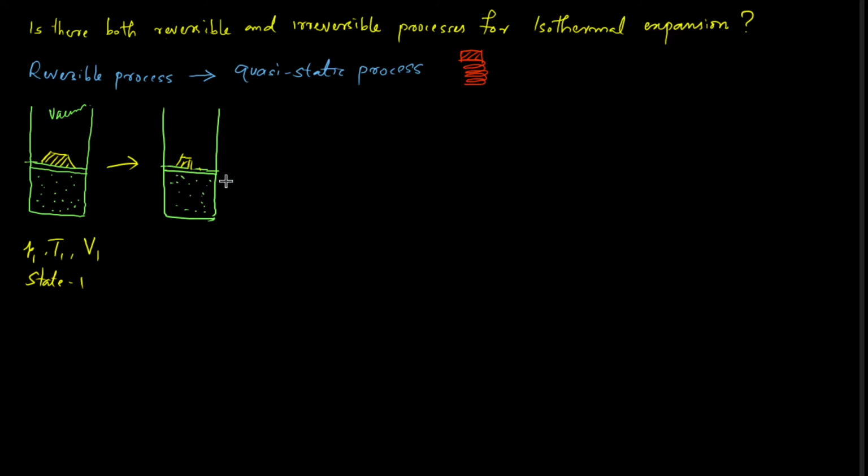So these particles will feel a low pressure because there is no force resisting it from the top. The system will be out of equilibrium, so this piston will move up. Since it happened very suddenly, the piston will start vibrating a bit, so we'll have some oscillations, just like the same thing happens when we remove a weight from the spring.